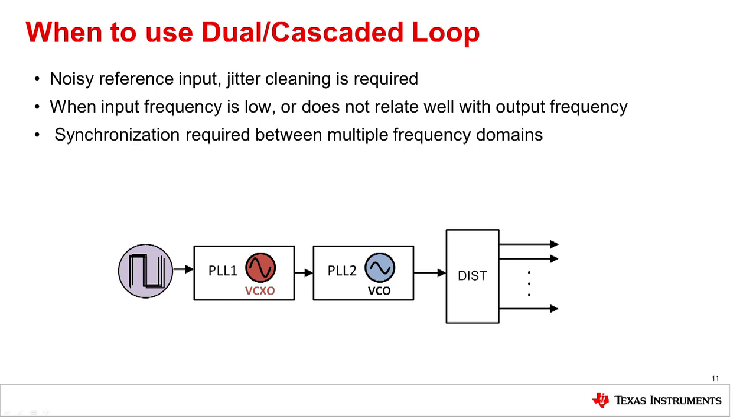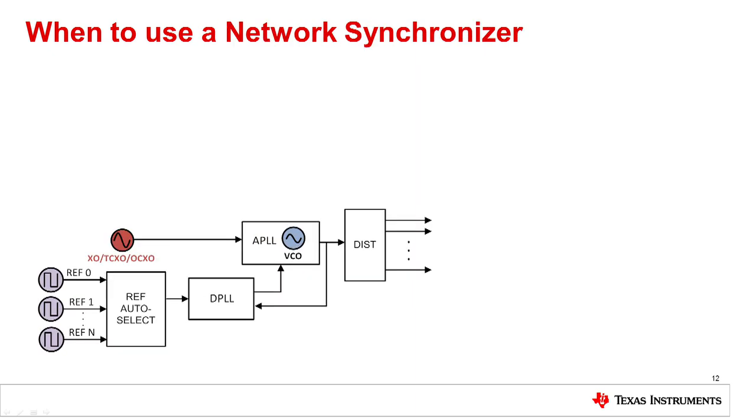Synchronization is required for multiple frequency sources, providing a deterministic phase relationship between input and multiple frequency outputs. Often jitter cleaners will include delay compensation networks in the distribution paths to help balance out any routing differences between the outputs. Synchronization, in fact, is becoming more and more important for time-critical applications, and to address this function, a network synchronizer is a key component that is often used to address some of the more challenging ITU telecom standards. Many ITU telecom and 4G, 5G standards dictate time and frequency synchronization be guaranteed at all times.